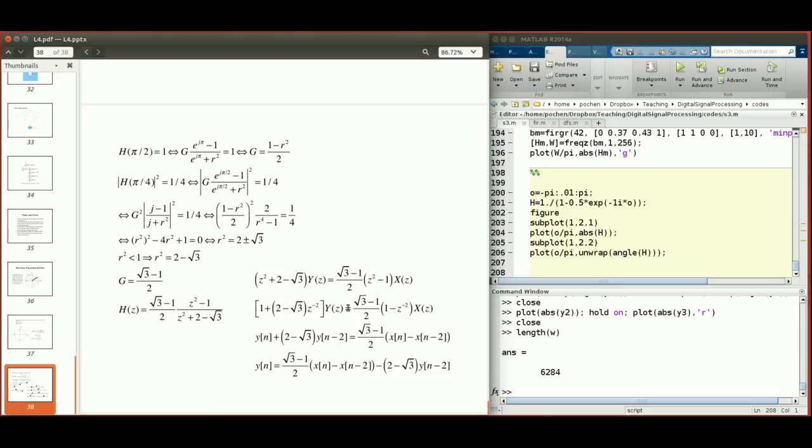So now we can start to convert it into a time domain representation. Big Y(z) multiplied by 1 converts into time domain as small y[n]. And then (2 subtract square root of 3) z to the minus 2 becomes (2 subtract square root of 3) y[n subtract 2]. The same thing happens on x. This is a constant 1 multiplying big X, which converts into small x[n]. And then z to the minus 2 times big X converts into small x[n subtract 2].